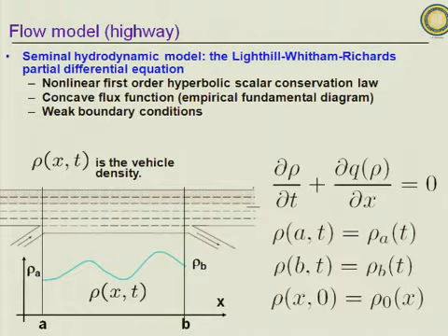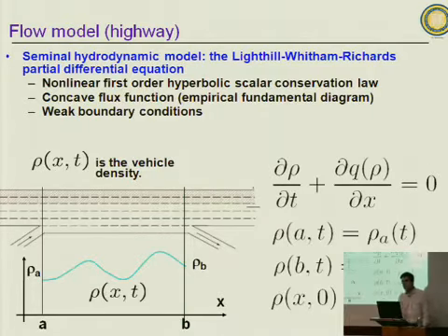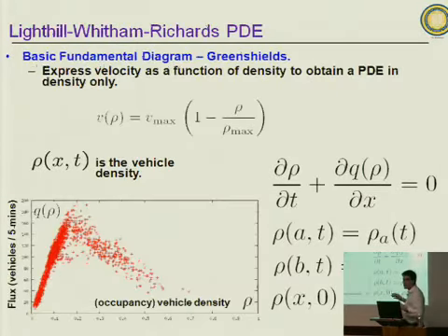Okay, so you have density of cars, which is modeled by a function which is space and time dependent, and its evolution is characterized by the PDE here, which relates its rate of change in time to the divergence of the flux, which is characterizing the inflows into control volumes in the system. Skipping the mathematical details, you have to go a little bit beyond imposing boundary conditions in the strong sense. You have to impose this in the weak sense, and I'm going to show this in a minute.